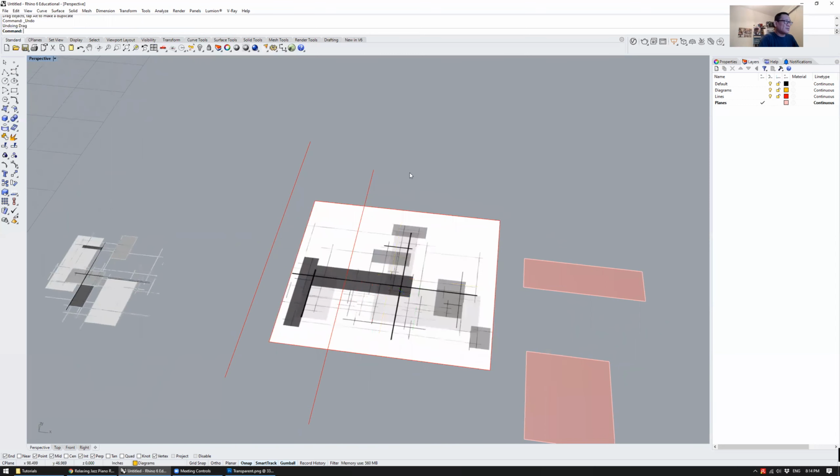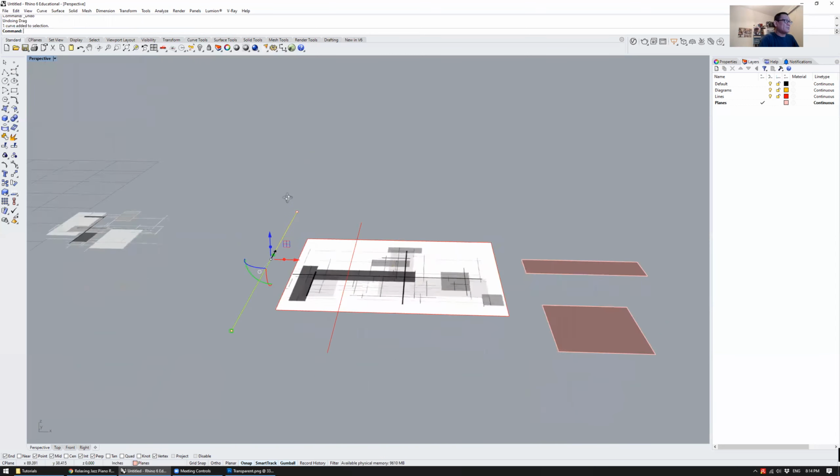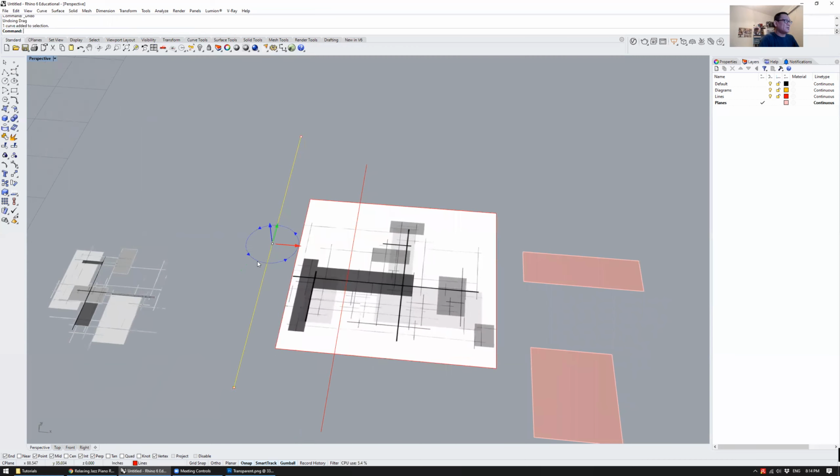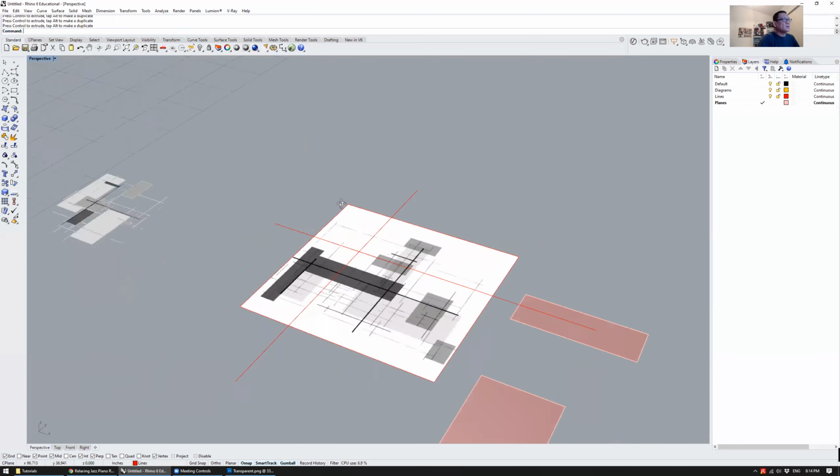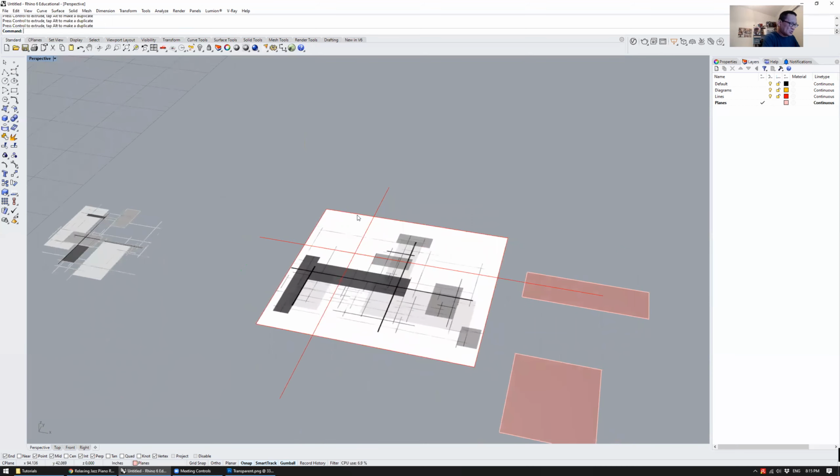You could get fancier with this. For example, if I took this line, let me turn it 90 degrees, holding down the shift key, so it's 90 degrees. And let me slide it somewhere else. Maybe, let's see, how about this line over here? Again, I can split, select object to split the diagram in the center here.